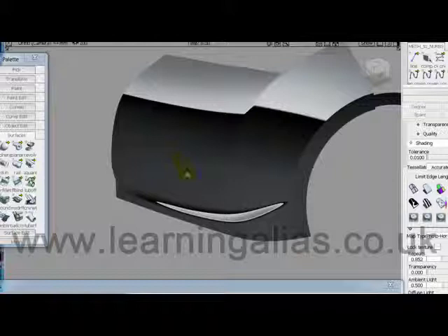And our problem is to create a transition surface between this light catcher surface and the body. So we're going to blend this light catcher surface into the body, into these two panels, and also we're going to bring this feature down here, which you can see is quite a hard feature there, and we're going to wash it out so that it disappears and forms a perfect transition into this boomerang blend. So all in all, pretty tough task. Well, let's get on with it and see how it's done.